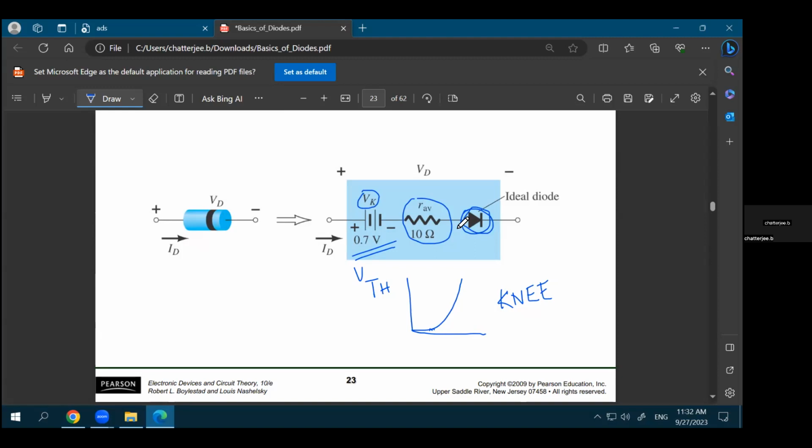So for example, if one diode has a 0.3 and the other a 0.7, it makes it interesting, because then you get a different kind of voltage. That will make things very interesting and very much complicated. If you want both diodes in forward bias, you have to consider the 0.7 volt drop across both diodes, which means one of the diodes will be just crossing the threshold. For the other diode, we have 0.7 volt threshold voltage.